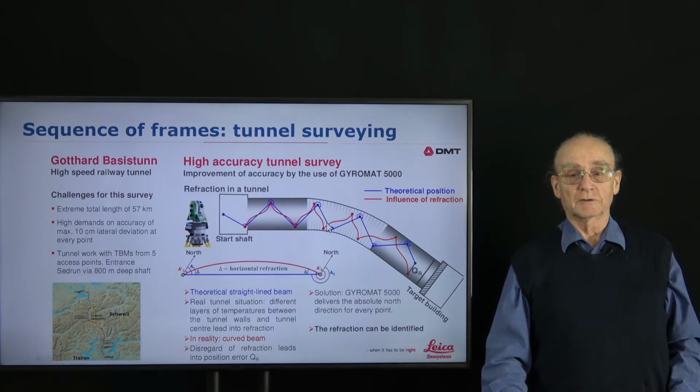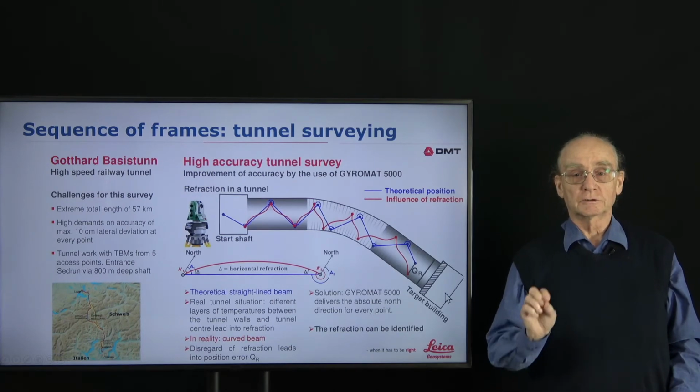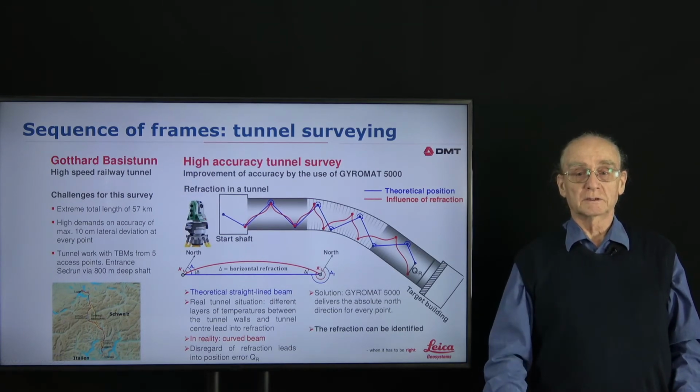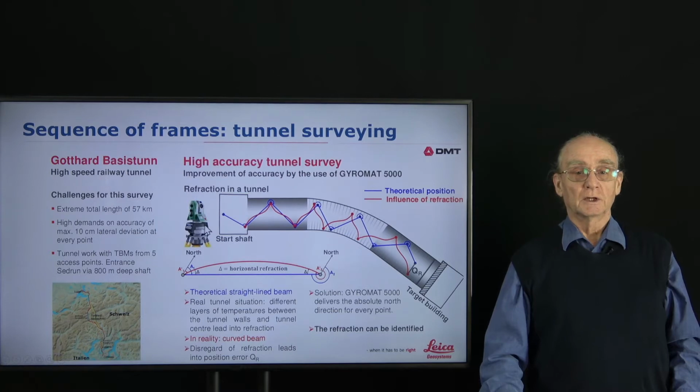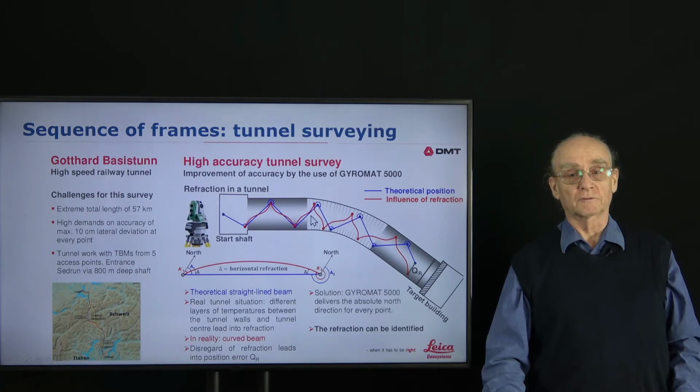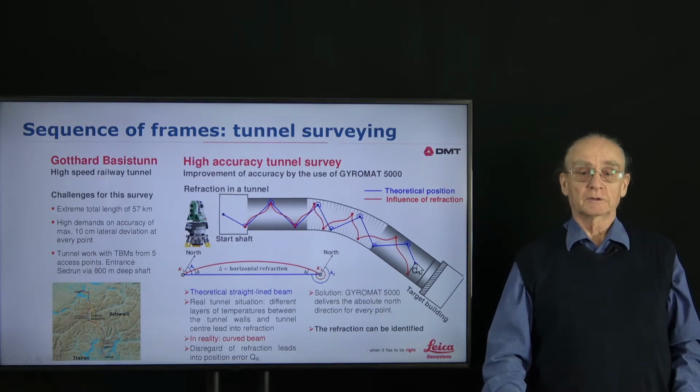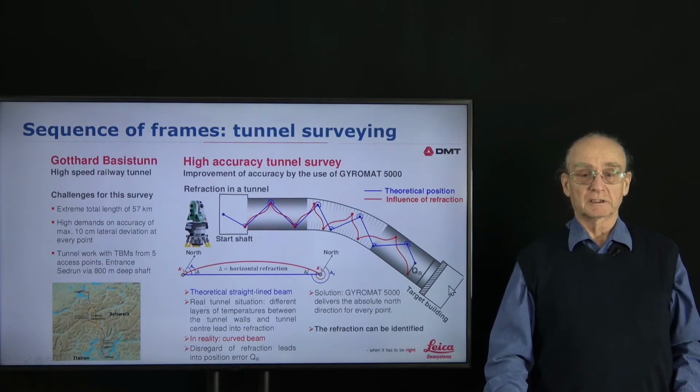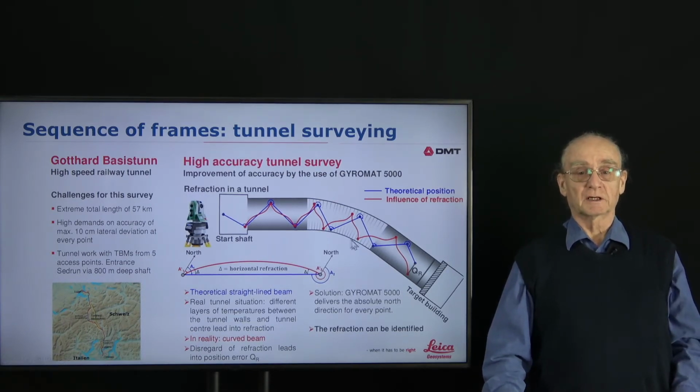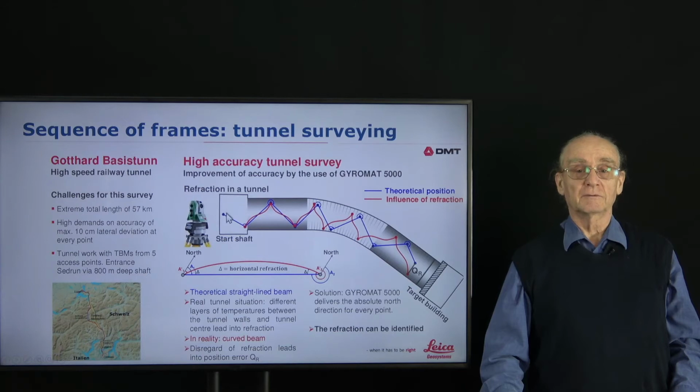So the idea is you have here the tunnel boring machine, which cuts out the rocks in the Alps, and you have here a surveying technology which enables you to have a sequence of points, actually of course coordinate systems, which is tracked until this point where the control of the boring machine is taking place. So this is a very specific type of kinematic chain, since it chains the individual coordinate systems here in 3D through the tunnel.